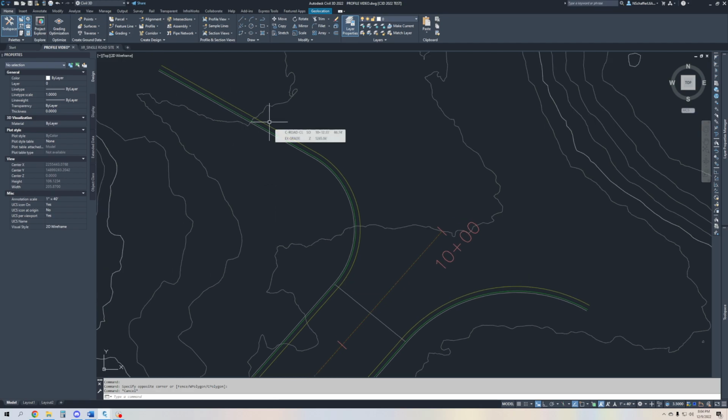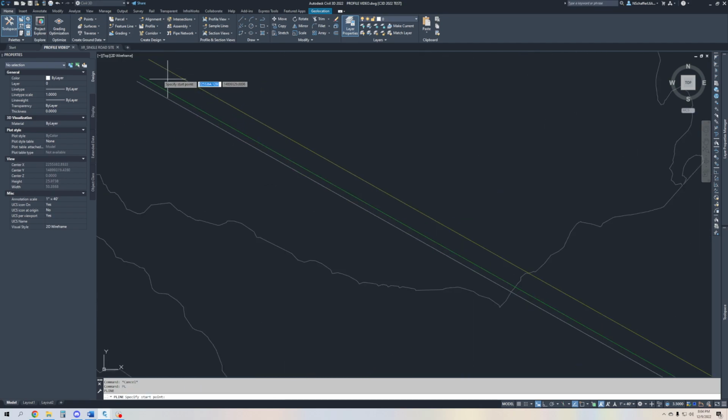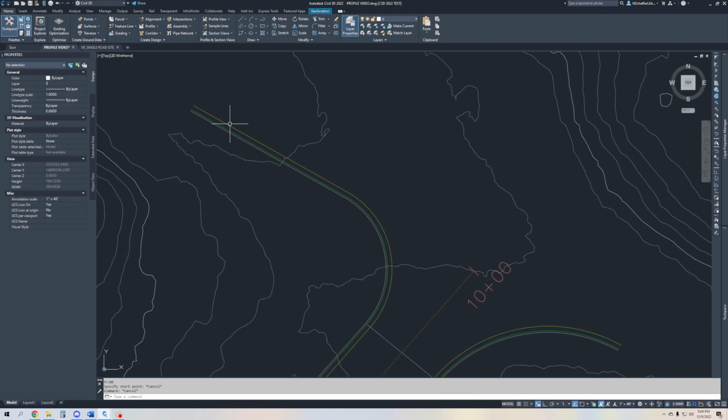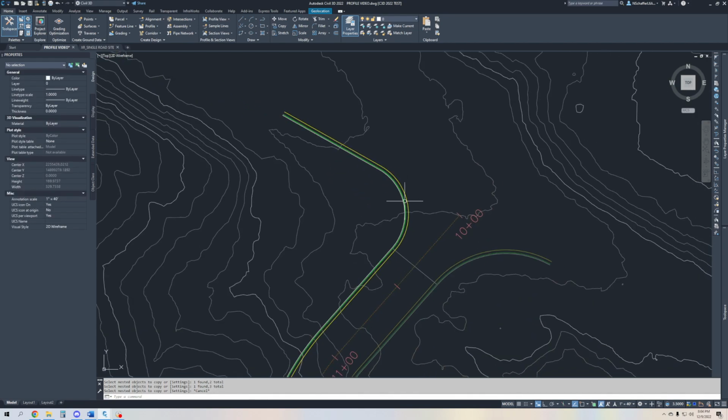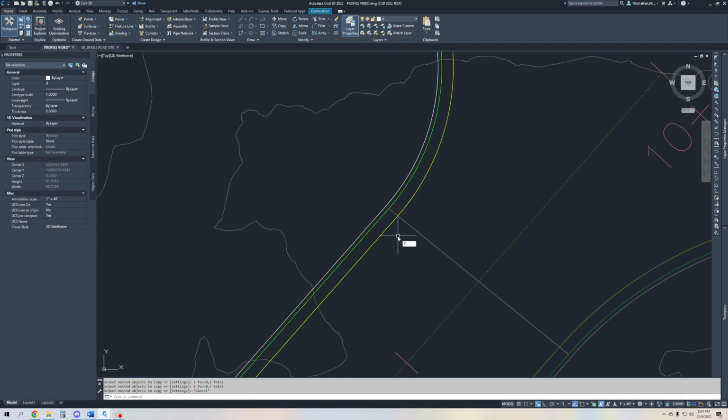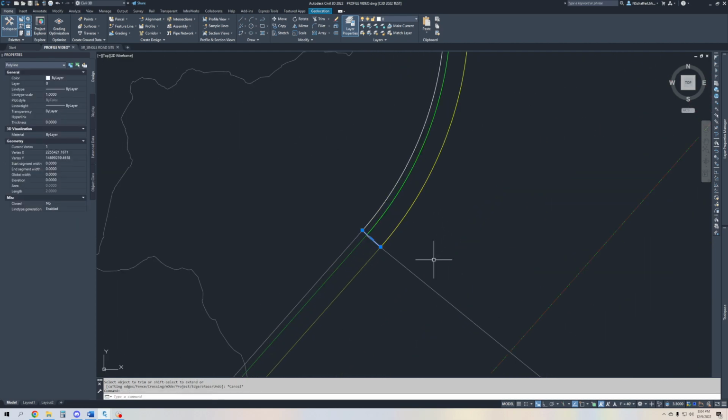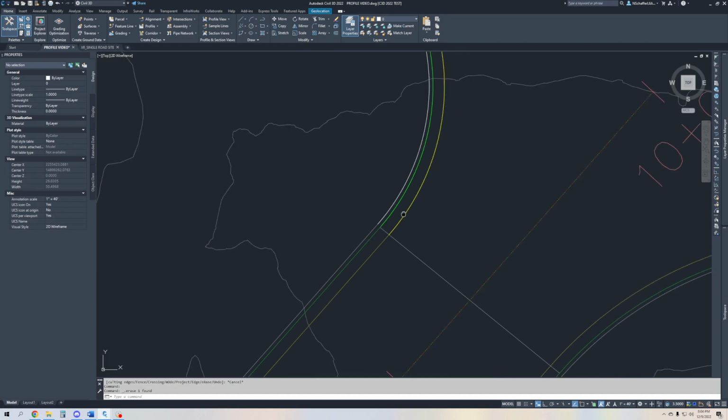So to start out, I'm going to do a nested copy really quick to get all of my objects in here, and then let's do intersection, and I'll select here and go perpendicular, and then I'm just going to go ahead and trim off the ends of those just so I have the lines that I want to do.